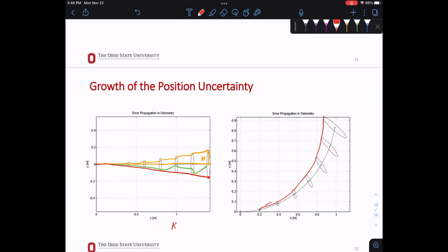I think KR was 0.1 and KL was 0.001, something like that. So when you measure and estimate those, this will be the position estimate, right? If this agrees with what you see, then when you're designing your PID controller, you're able to compensate properly and go back to a straight line, right? So this term is called position estimate, but you're estimating the amount of error.